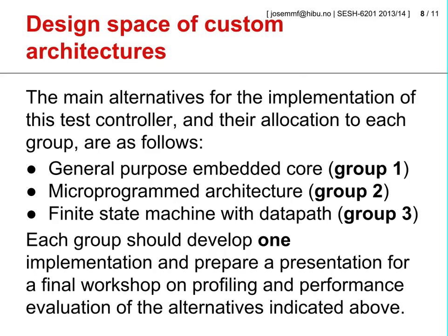So actually there are 3 main alternatives for implementing this test controller. We could envisage implementing it as a general purpose embedded core, be it the PicoBlaze or the MicroBlaze soft cores from Xilinx. It could be implemented as a microprogrammed architecture, or it could also be implemented as a finite state machine with data path, or FSMD.